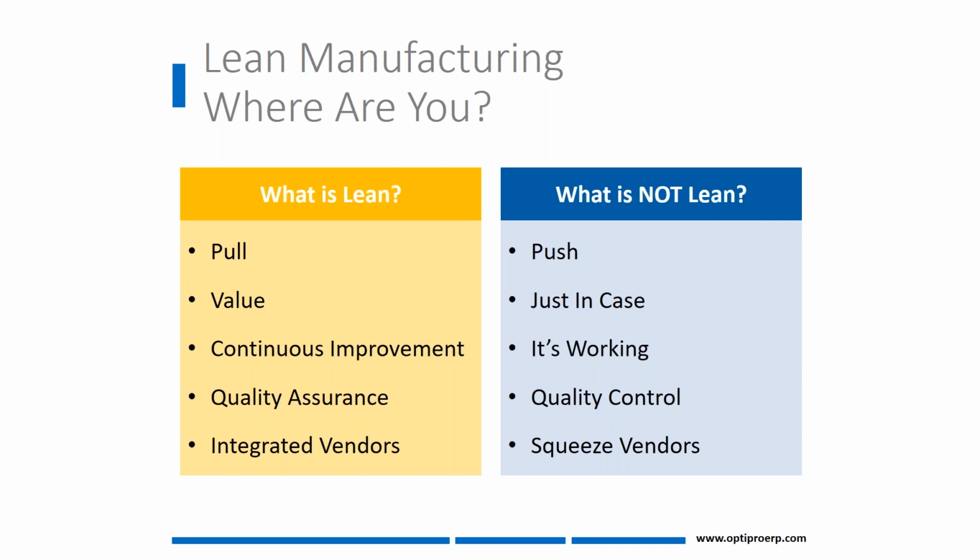Traditionally we say, well, of course, let's tie down all the tolerances, make them really, really tight, and we'll make a good quality product. Well, the reality is, the time spent to get two tenths versus the time to get two thou are vastly different. That difference is money, and that difference, quite frankly, costs your customer, and therefore it's an opportunity for us. Again, look at the different concepts. Where are you? Are you traditional or are you pushing lean?